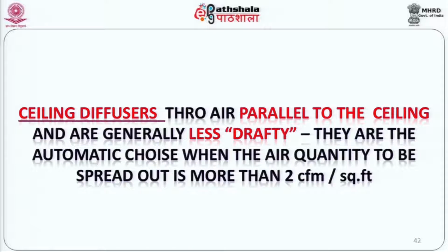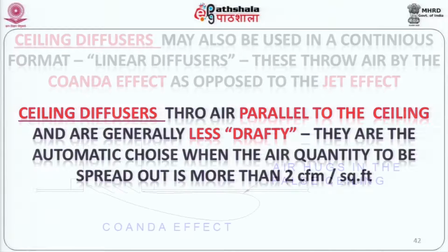You have the air quantity being spread into a large space, and ceiling diffusers become absolutely necessary in places where the discharge air quantity, this is a small parameter which is very common to an air conditioning specialist, exceeds 2 CFM per square foot or 20 meter cube per square meter. One automatically has to use ceiling diffusers because the sidewall grill will become too drafty.